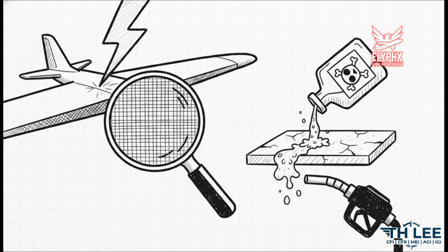Lastly, chemical hazards. Never use chemical paint strippers on composites. They will literally ruin the matrix. And if an aircraft uses inexpensive polyester resins for its fuel tanks, ethanol-blended autogas can actually attack and dissolve the composite, though more expensive epoxy resins handle it just fine.